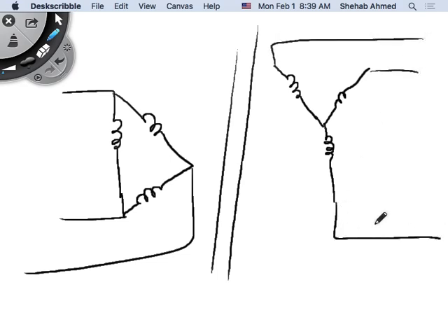We will agree together, I think in the next class or the following one, that when we draw one of these transformers, any of the windings that we draw in parallel with each other will be the same phase. So we will agree to that internally here, and this is sort of what electrical engineers like to agree to. Physically, the way we drew it here on paper, we drew this in parallel to this, right? So if I call this phase A, then this is AB, for example. This is phase A of the delta. So this and this, the parallel windings, are on the same core.